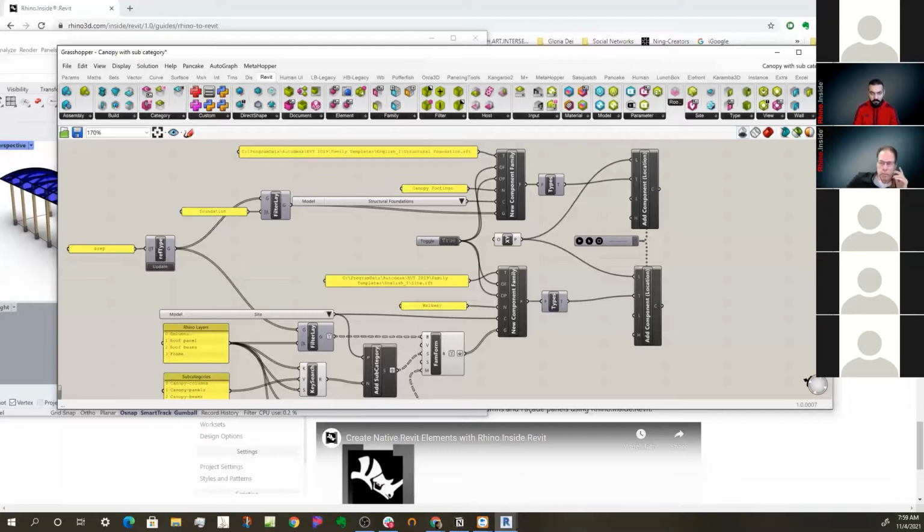And so if you wanted to change the height of the wall, you're actually not touching the family definition itself. The walls have their own built-in families because it's a system one, but you're not touching the family itself. What you are doing is changing the height parameter on it. So you're going to come back on the object and say, give me its height, I want to set its height parameter. And let me see if I have an example. Yeah, I might have an example. Let me show you how you do that.